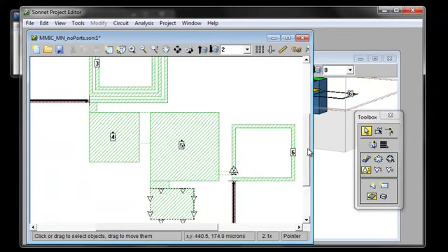So now what we will do is simulate this structure in the EM simulator, develop a 6-port S-parameter data block, and import that into a circuit theory or network analysis tool. In this case, we'll use the AWR Microwave Office software. So I'll show you that in just a second.